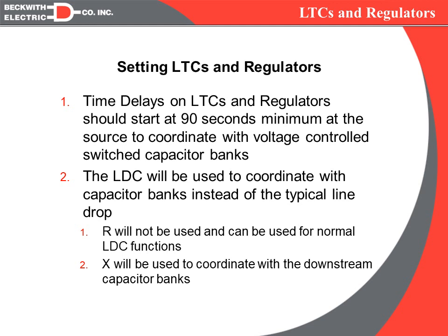The other thing we're going to look at is now we need to coordinate our regulators and our LTCs again with capacitor banks. And so the first phase of that is to have a longer time delay to allow the banks to operate. But we need to make sure that we don't have too many banks operating. We do want to see a slightly leading power factor, but we've got to remember that too much leading VAR current is just as bad as too much lagging VAR current.